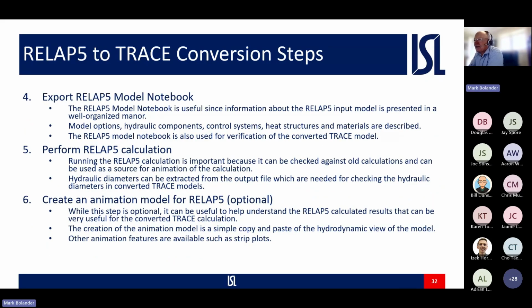Then it's suggested that you export the RELAP5 model notebook. Isaac pointed out how to do that in the first exercise, and it's going to be useful since your information about the RELAP5 model is presented in a well-organized manner, and it helps you when you're looking for errors or issues with your converted TRACE model.